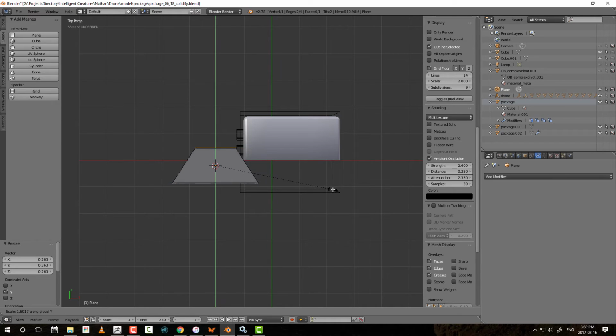So scale again, press Y, constrain, and okay, there you go. So basically what I wanted is to make sure that this line is perfectly smooth. And what that means, and this is from experience, is that when a line is perfectly smooth, it's going to be either perfectly straight, horizontal or vertical, or at a 45-degree angle, right?